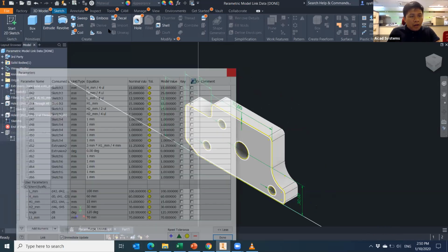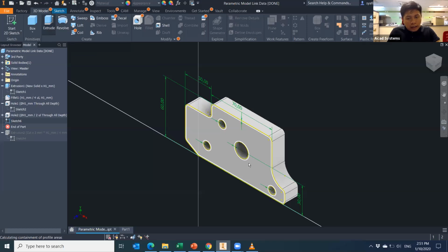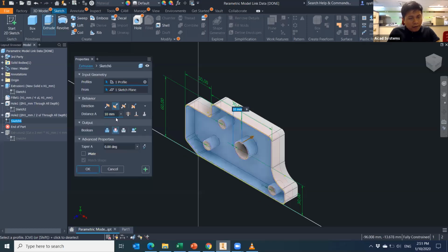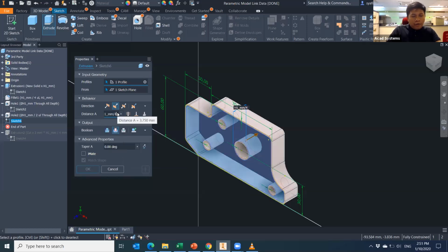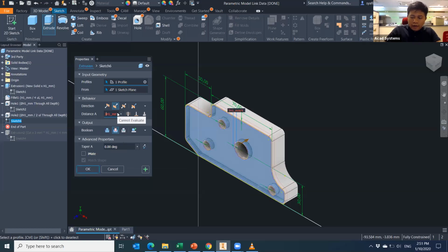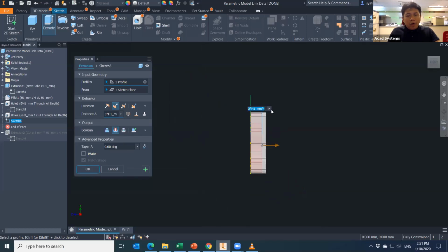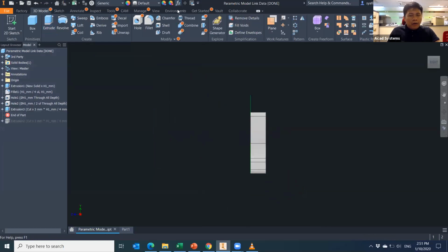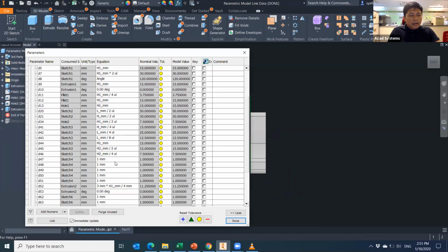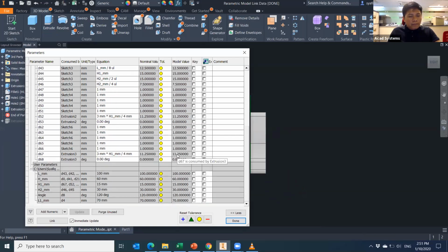Okay, I need to use H1. Extrude, here, flip, click on list parameter H1 divided by 4 times 3. 3 times H1. Okay, the size will always follow the total length here. Then hit OK. When you click on the parameter, the newest one will go at the bottom.